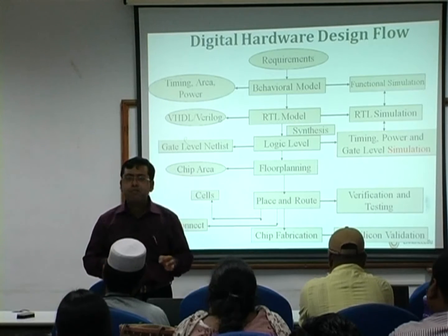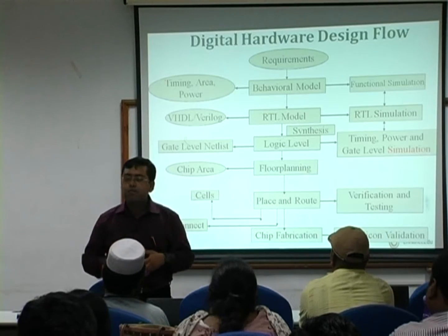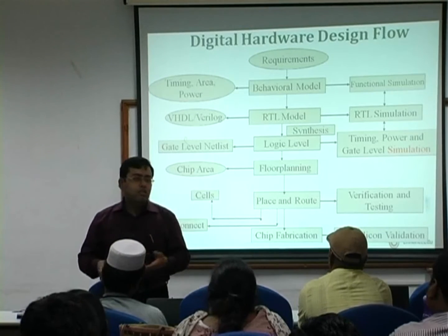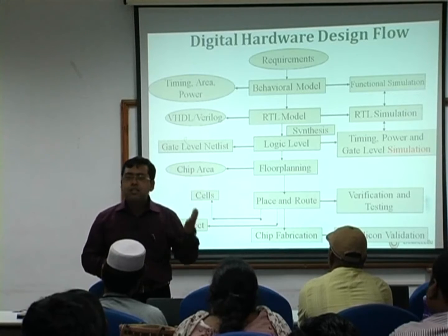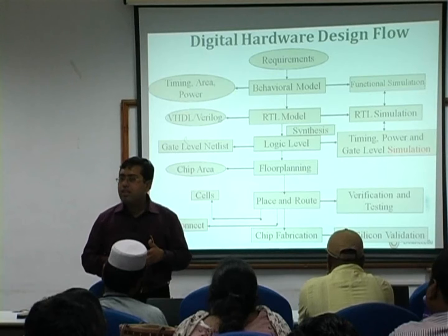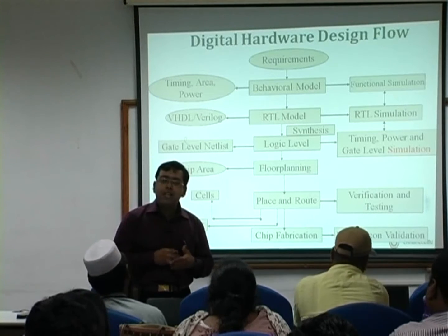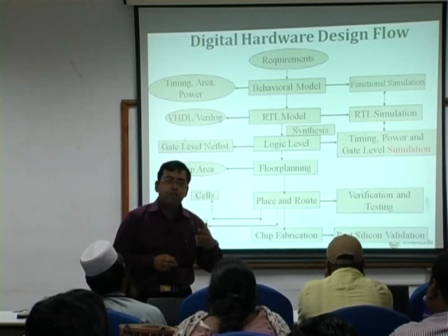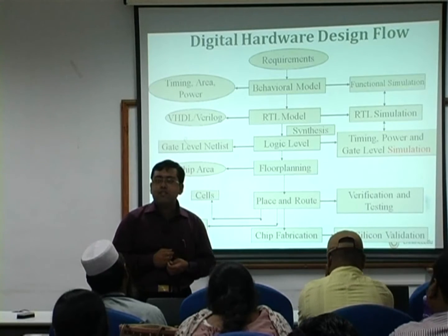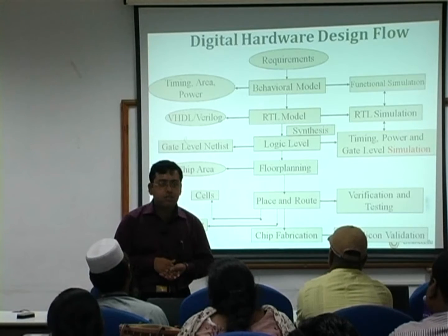For example, a certain component can be shorted to the VDD, or a certain component can be shorted to the ground. There can be circuit breakages of interconnects at certain points or the other. So they can lead to lots of anomalies in the circuit behavior. So once you test it after manufacturing, all these defects are typically excavated.